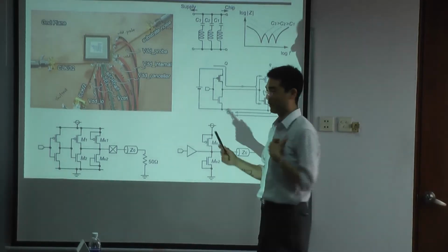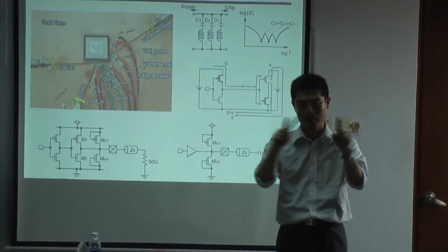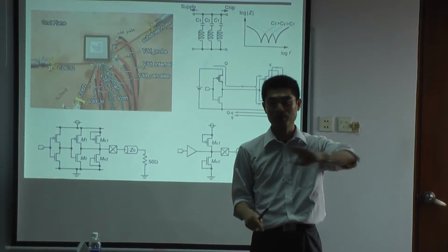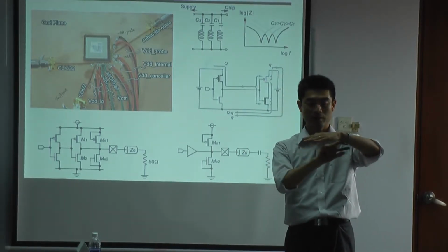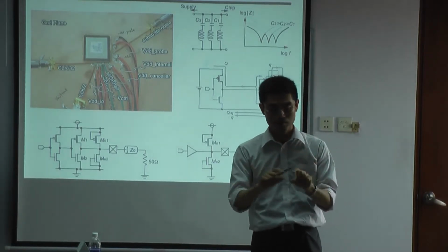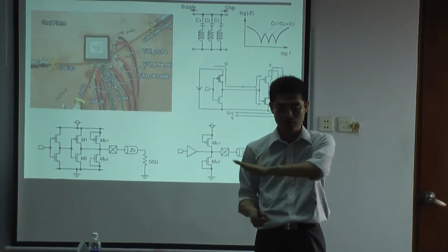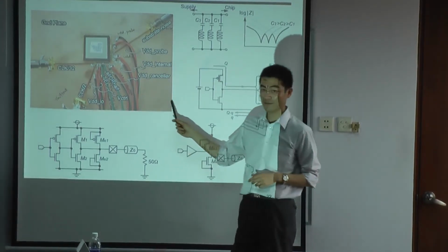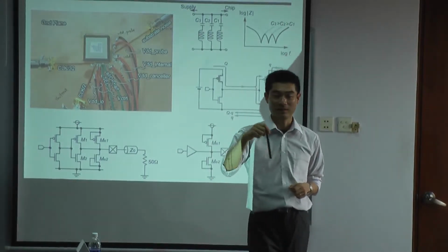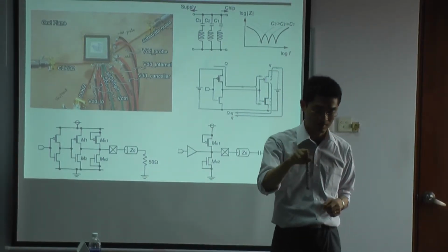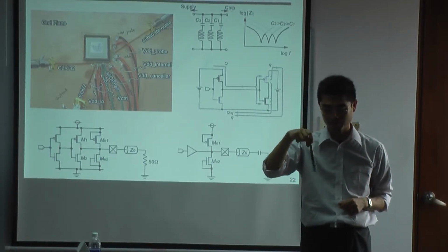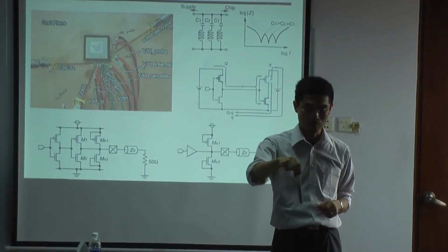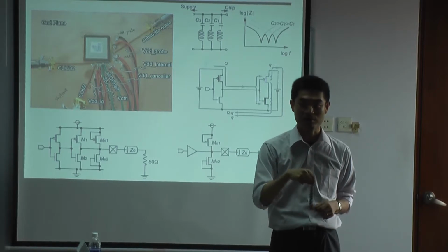We have a board about this size, like A4 size. The surface is covered by copper, and mainly it is an FR4 board. And there is a machine with a rotating needle that will scratch and write a pattern on the board, so that only the copper parts are scratched out.